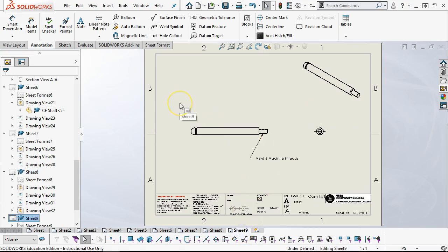And then the last one was to bring up the spherical radius. So there's not anything really critical here. I would think that we could do a precision ground shaft, concentricity within a couple thousandths, and size to fit inside of the bushing would be fine.